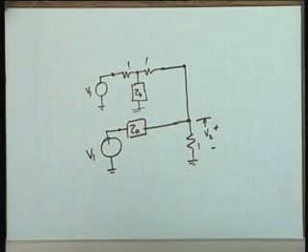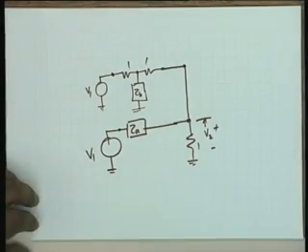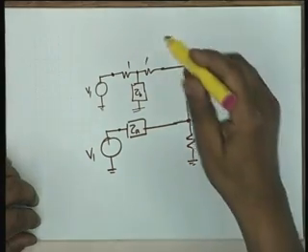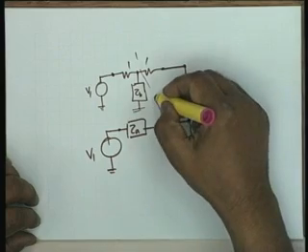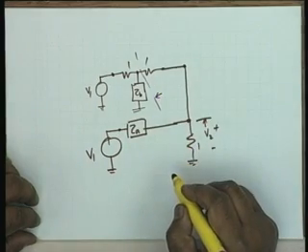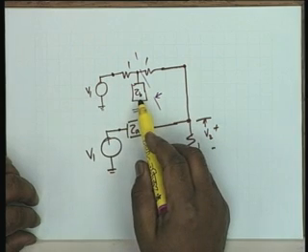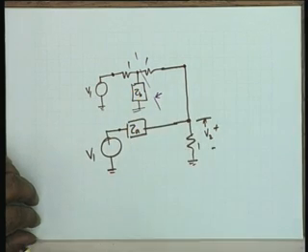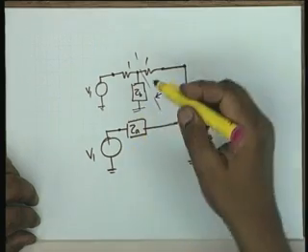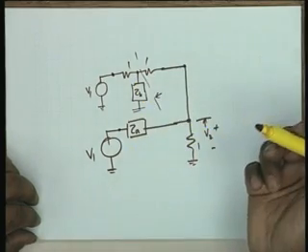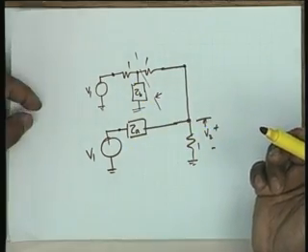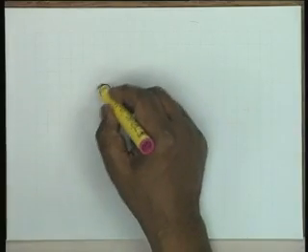Potential is V1. Now you see, as far as this network is concerned, it can be solved almost by inspection, because if we apply Thevenin's theorem here, then the equivalent would be V1 ZB divided by ZB plus 1, equivalent voltage source, and the equivalent internal impedance would be 1 into ZB divided by 1 plus ZB. Okay, so I can draw this by inspection.